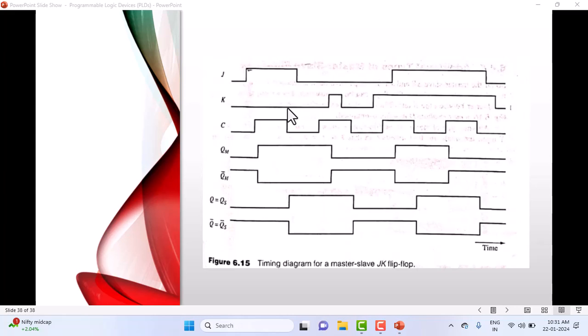And again, this is just like the previous timing diagram, the way I've explained here. I'll only tell you the toggle mode. Where is the toggle mode here? Can anybody explain? Where can you see the toggle mode in this waveform? This is the toggle mode. Both are 1-1. Look here. Both are 1-1, clock is 1. What is happening here? 1, 0, 0. And this has propagated the data. You can see 1, 0. Are you seeing this? This is called toggle mode here.